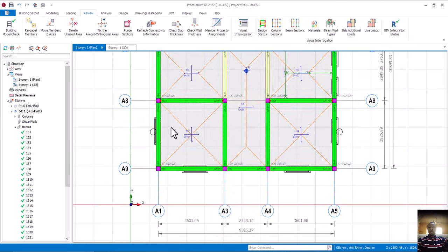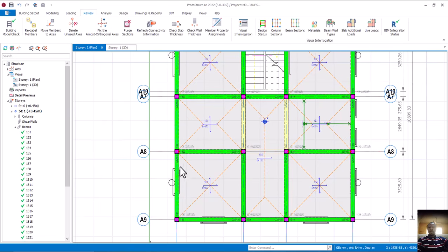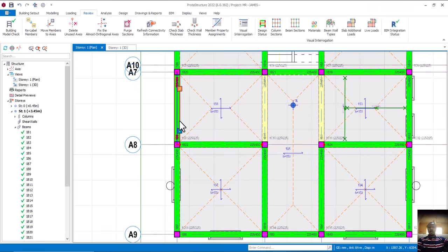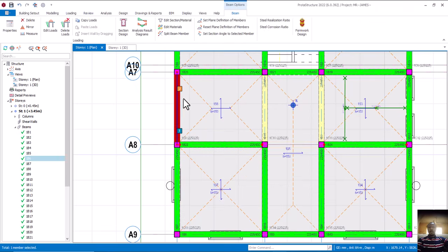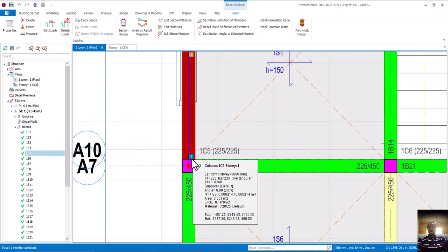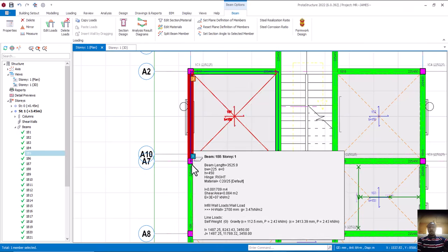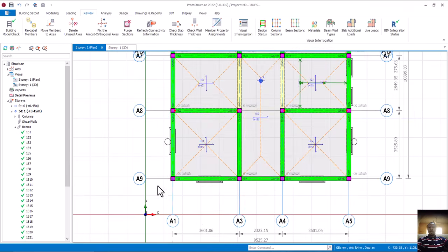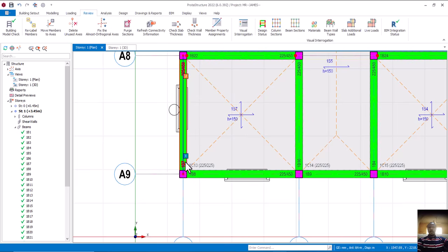So that is fine. Having done that, coming to this particular beam, you discover that we did not hinge it at J. And for this particular beam also, we are not hinging at I and J, isn't it? And for this one also, we are not hinging at what? At I. Why? Because it's a continuous beam, isn't it? So that is fine. Now coming to this place, in this case, I have to hinge this place.